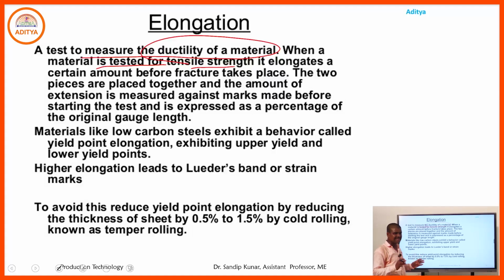So we take elongation up to our limit, as per our requirement, not before that. The two pieces are placed together and the amount of extension is measured against the marks made before starting the test, and expressed as a percentage of the original gauge length. So we always take care about the elongation of that particular material.